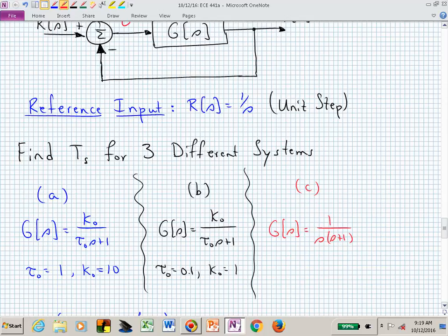What's the DC gain of G? It's blowing up, isn't it? It's unbounded because we have this integrator at the origin. We have a pure pole right at the origin. Integrators always are a pole at the origin. We have one pole at the origin, and we'll call that a type 1 system. But this one now has much higher gain at DC than these other two.